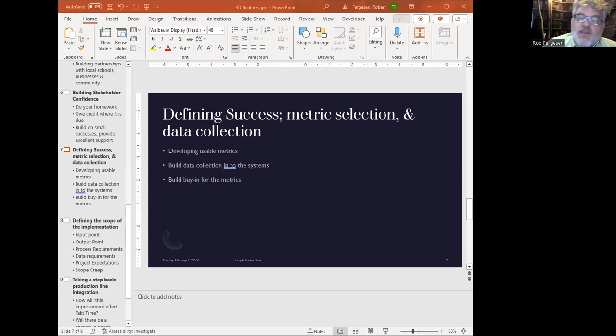And that leads me to the next area, building data collection systems. You have to build data collection for your metric into your plans for your project. PLCs are the best way to do data collection in that sense. You can do your counts, you can do your timing, and you could hold that data. However, the data sitting in a PLC register is of no value at all. So you will need to have some sort of higher level system to collect that data inside of a PLC.